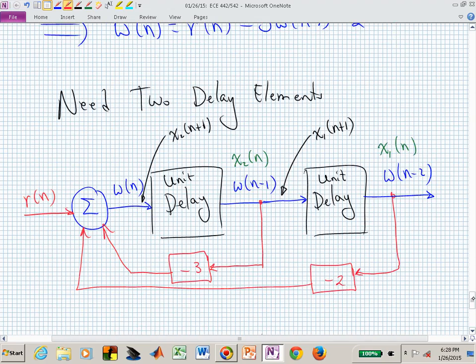That's right there screaming at you in the block diagram as you designed it. What's x sub 2 of n plus 1 equal to? This one has a little bit more character to it. And again, you don't want to write anything in terms of n plus 1s on the right-hand side. You only want to write variables, state variables and inputs at the present time n. We have minus 3 x sub 2 of n.